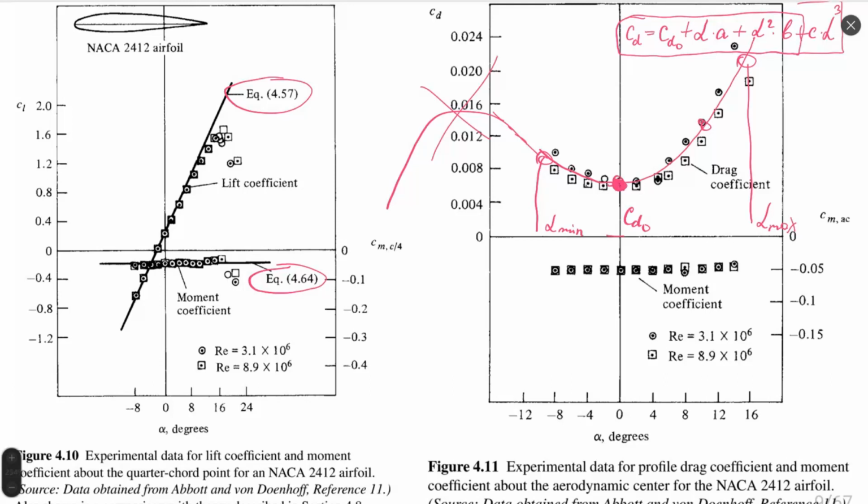So because of this, I say linear approximation, just with the functions without square, just CD0 plus alpha A for each region, would be the best option, because it never will lead you to overestimation or big underestimation of the aerodynamic coefficient. It will always give you something in the middle.